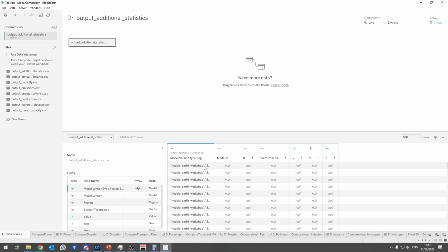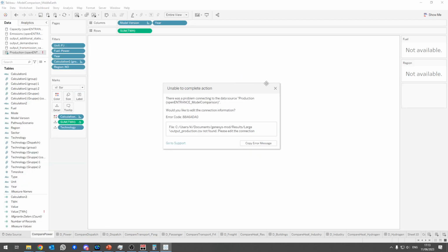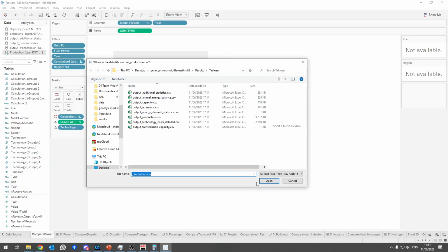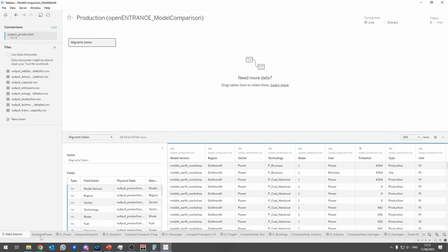And then we will see that in my case, the CSV format was not correct. So in my case, I need to change this to be field separator, comma, and then everything will work again. It's sometimes a little bit wobbly in that regard, that sometimes, due to your regional Windows settings, it might expect a comma, or it might expect a semicolon instead. In our case, we want a comma. And I have to do the same again for this file. Most likely I don't have the exact same problem.